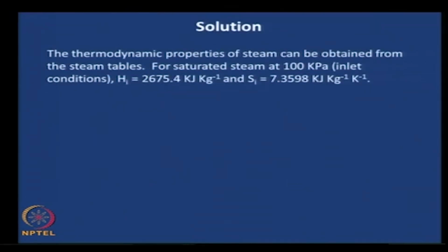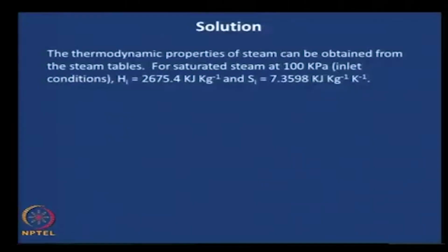Let me start you out with the solution, and then you can take some time to work it out, then I will give you the final solution. The thermodynamic properties of steam can be obtained from the steam tables. For saturated steam, you need to look at the saturated steam tables, either on the line for the PT diagram or under the dome for the PV diagram. You need to have this idea in mind when you look at steam tables.